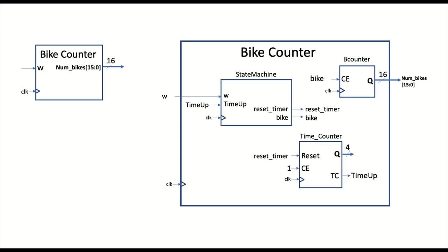Okay? But once you set the load input to 0, the input bus, the D-in bus, you can just leave unconnected because it's not going to affect your counter as long as the load is always 0. So we happen to know that making the D input a don't care is not a problem for the counter because the load is always 0. Okay? If you're worried about it, you can just always specify your inputs. Just set them to 0 or 1 according to what you want.